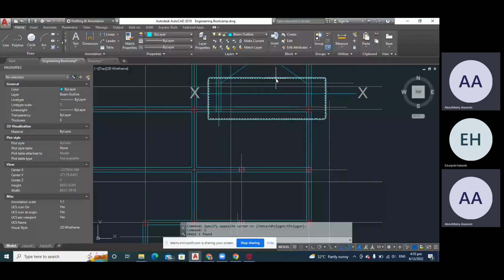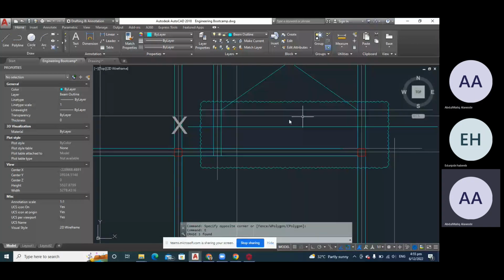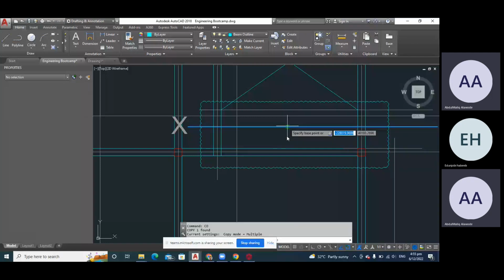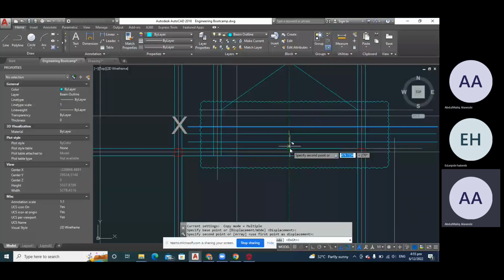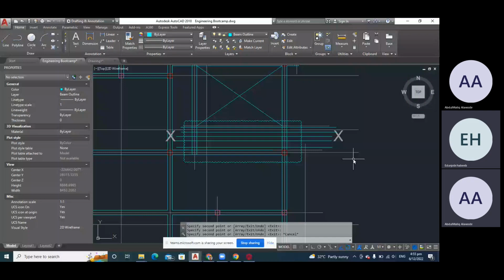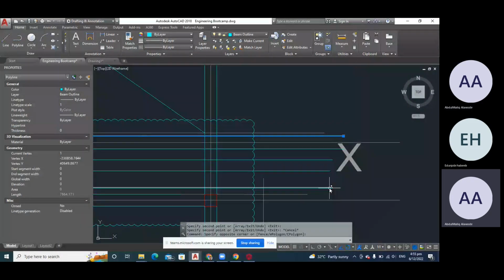So this beam and this beam in here are going to be the receivers of the load. And when they are laying reinforcement on site, they are going to lay this one first. Do you understand? Yes, sir. So that is what the strip is talking about.